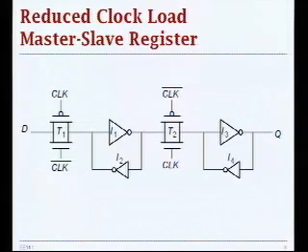So let me go back to slides and show you first the implementation of this master-slave register. So when a structure is edge triggered, then we call that a register. When it's level triggered, we say that is a latch. So what we have over here is, remember, there were two mechanisms that we can store the state into a latch. There was this mechanism where you can overpower your state, or there is another way where you can basically break the feedback loop, inject the new value, and then close the feedback loop to hold the state.